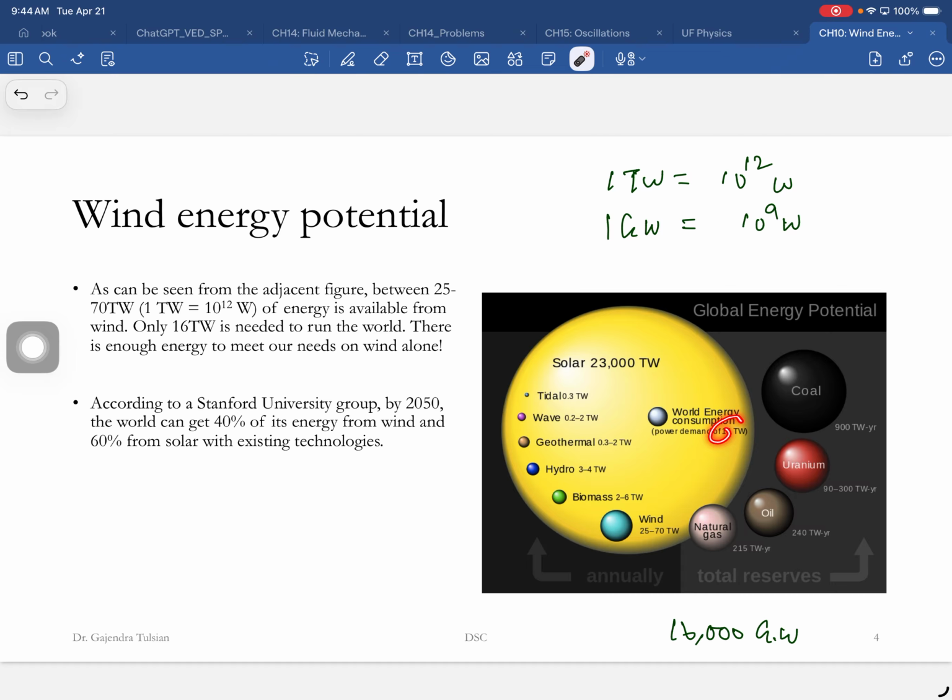If the blade spins too slow, then most of the wind will pass by the rotor without extracting energy. So if the blades are rotating too slow, all the wind is blowing by and you're leaving that money on the table. If you turn too fast, then you're going through turbulence and you're wasting your efforts. If the blades spin too fast, each blade will always be traveling through turbulence of the blade in front of it and not capture energy. So you have to rotate at an optimal speed.